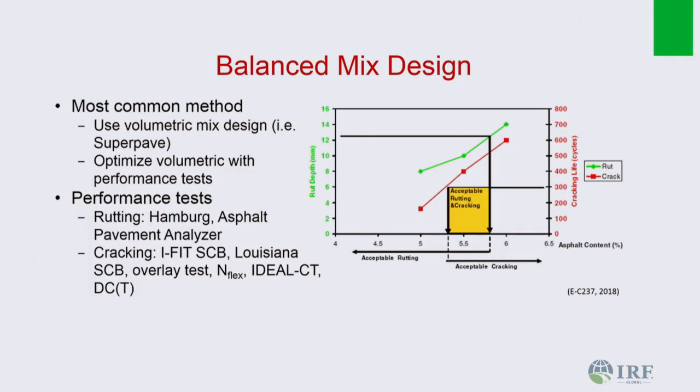But let the pavement go through this quick number of cycles to know how it will perform in future, and what are the cracking, what are the rutting that will happen in that future. So you are simulating it so it's able to tell you maybe within a month or 3 months what will happen in 20 years.